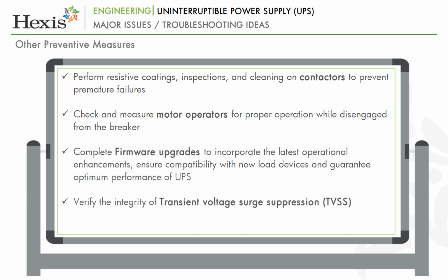It is important to verify the transient voltage surge suppression, that is TVSS, integrity, and ensure that metal oxide varistor, that is MOV, devices are functional and have not been compromised by excessive transients.